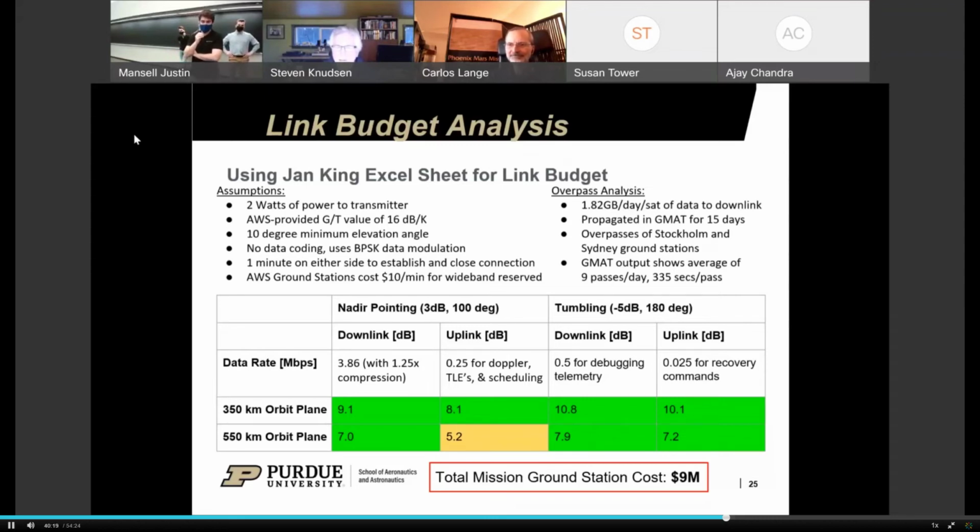Right. So compression, one of the big drivers that we found here was that the data rate we were trying to convey is one of the big drivers for this number. We were kind of constrained because we initially were using horn antennas, which had a much higher peak gain, but had a much smaller field of view. And this field of view proved really difficult, both in terms of minimizing your viewability of the ground station, as well as for a tumbling or off nadir, like not nominal pointing scenario.